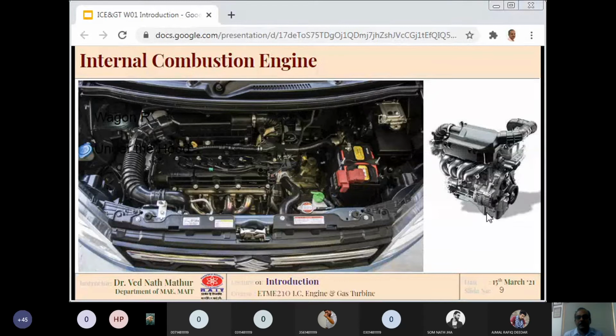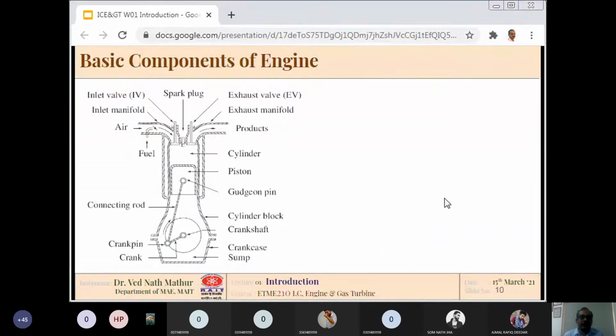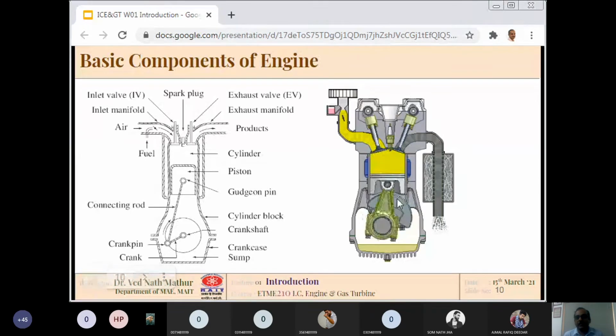What happens is there's a piston inside the cylinder, which reciprocates inside this cylinder. So there are 4 such devices. I'll show you an animation. This piston reciprocates up and down. When it comes down, it pushes the crankshaft, which rotates, and this rotational energy is then transmitted to our wheels by way of the transmission system, which consists of clutches, gearbox, propeller shaft, drivetrain, etc.